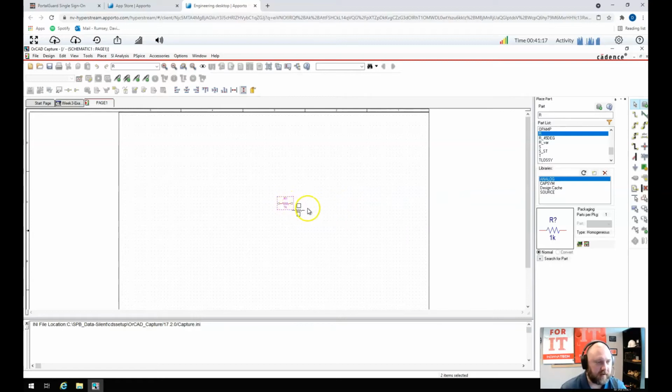but by left clicking on there, I actually placed one component. Instead of doing that in the menu, I also am going to say that if you use the R key, you can rotate them. Now, I'm going to rotate this just so that the resistors are all in the direction that they were in the circuit diagram.